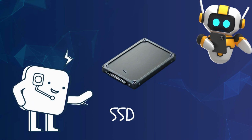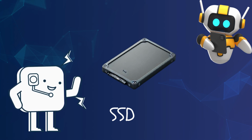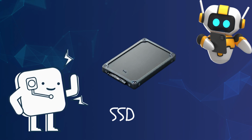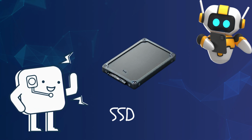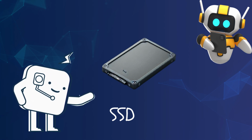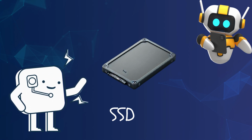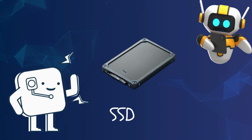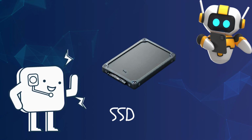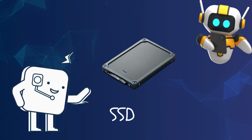SSDs have a limited lifespan due to a finite number of program erase cycles. To mitigate this, manufacturers use error correction to recover data from marginal cells, over provisioning to add extra flash capacity for better data management, and specialized firmware algorithms to manage cells efficiently.